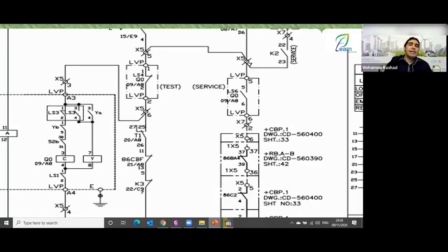When does it close again? As soon as the breaker opens. So what does this mean? What do you want to do as soon as the breaker opens? Don't close this contact immediately. I want to wait for a period first and then close this contact. Why is that, engineer? Because this is a capacitor. When it was operating, it stored electrical charges inside.